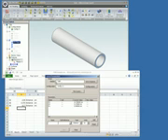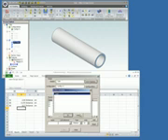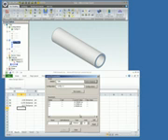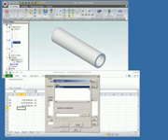The part name is displayed in the Design field, and its dimensions appear in the Parameters table. Since the tube part file is the only part file currently active, the name of the part file is displayed in the Session box. If more than one part file was active, you would select the desired file by clicking on Active Sessions and making a selection from the list. If there was more than one part configuration to choose from in the part file, the Configurations button could be clicked and a selection made from that list.